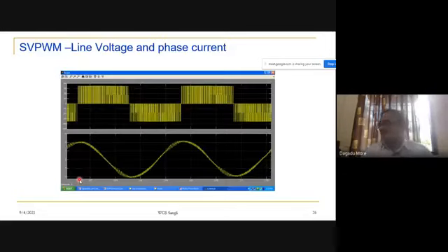And this is the output phase voltage. We simulated it with MATLAB, and this is the phase voltage. It will switch between plus VDC and minus VDC magnitude. If only the waveform is shown, we cannot identify whether it is a sinusoidal PWM output waveform or space vector PWM. You cannot clearly identify that.